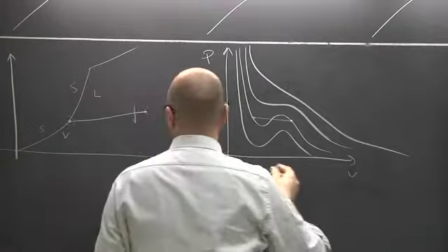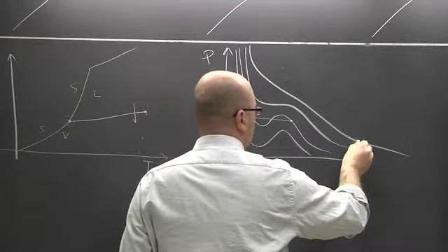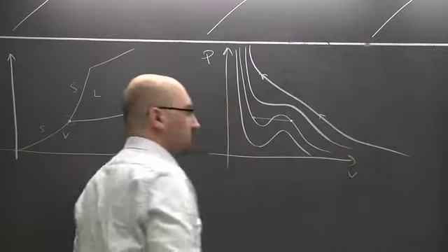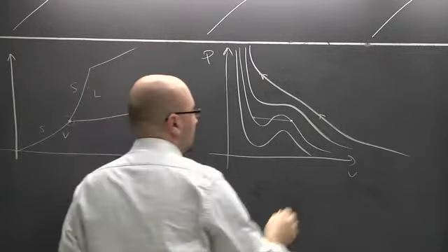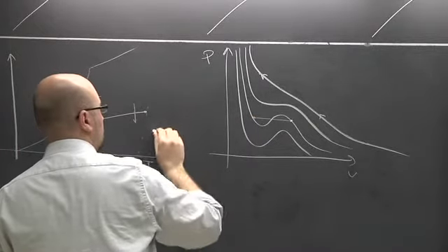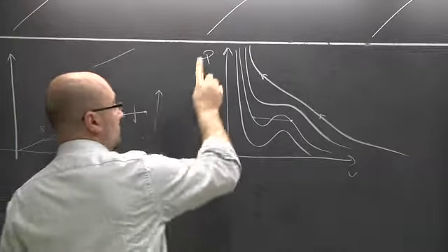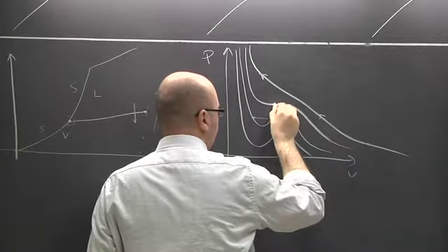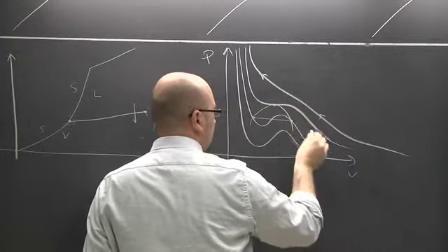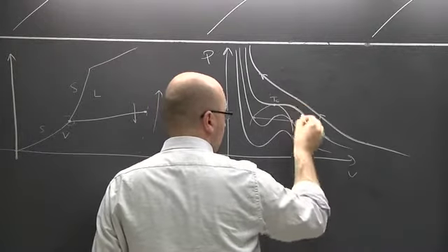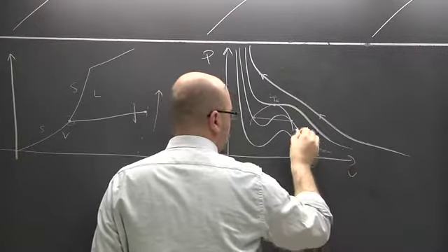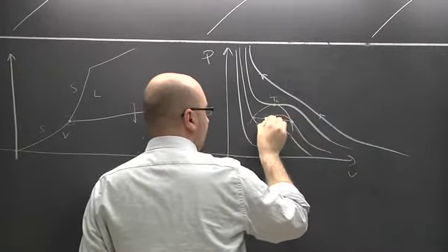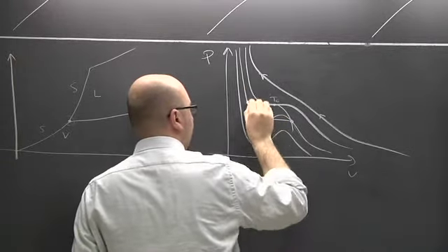If I am above the critical temperature and I compress my system, the pressure changes, but there is nothing strange in this direction, going in increasing pressure. But here, if I do this from this temperature down, when I compress the system, my gas starts liquefying, and then it becomes all liquid, and then goes up here.